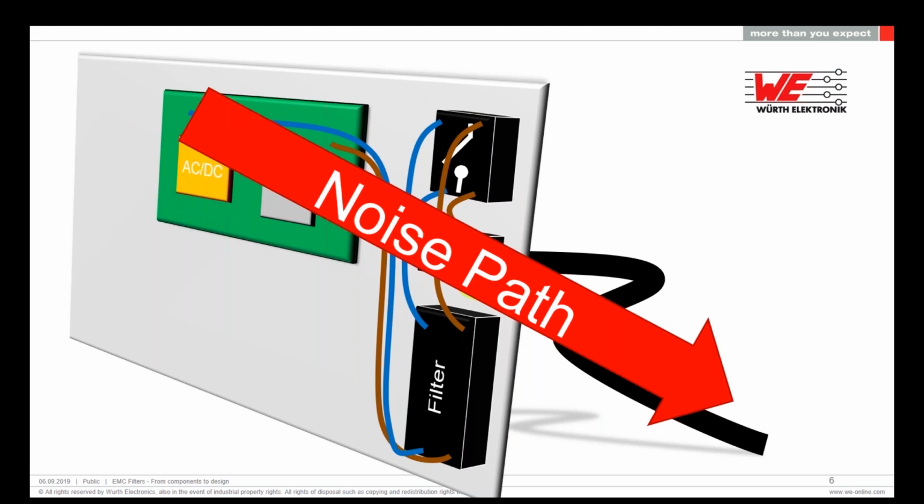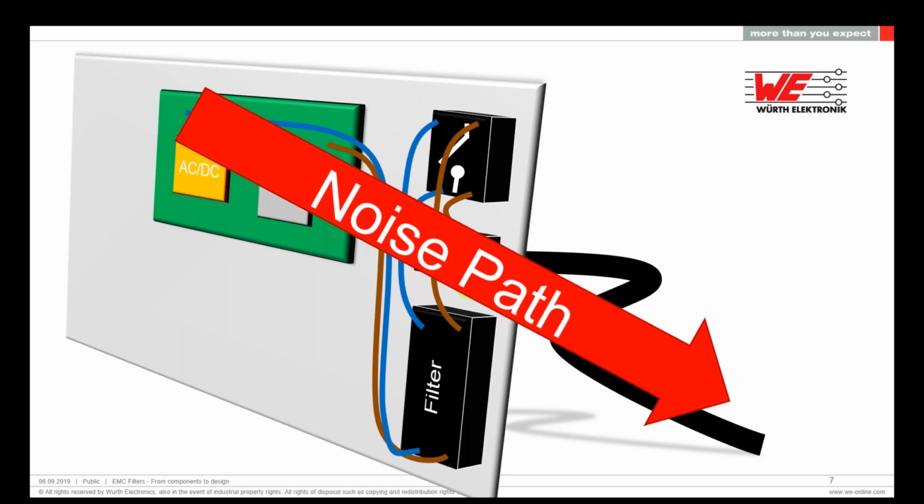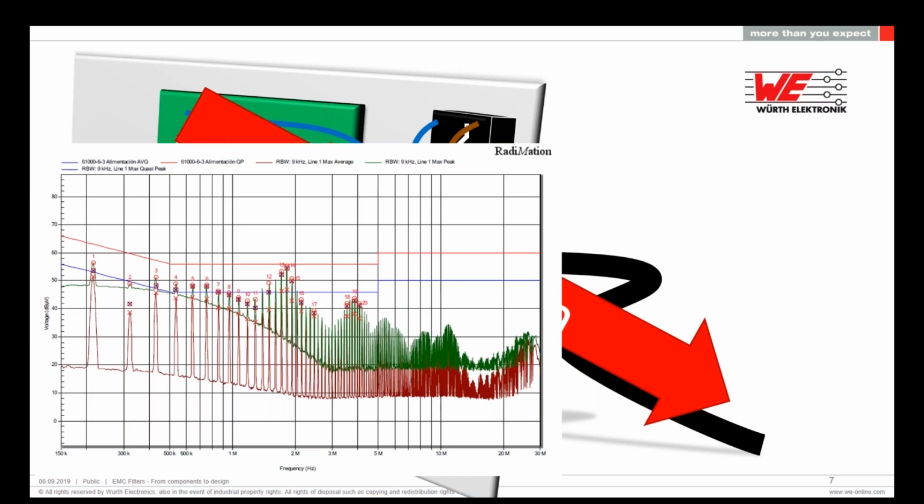So basically what we saw from the customer, or the picture we received, was the conducted emissions. And what we see detailed in the picture is that we have the harmonics at the different frequencies, basically at 210, 320, 430 kilohertz. So what we can imagine is the customer had a DC-DC converter with a switching frequency of around 105 or 100 kilohertz.